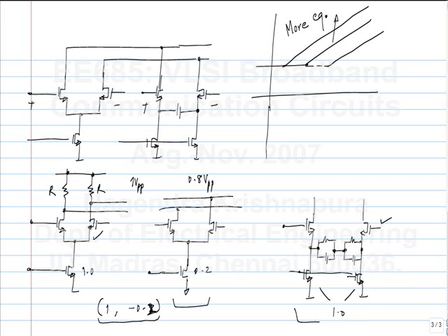Maybe this will consume lower power for a simple equalizer like this. But the advantage of the FIR equalizer is that you can make more complicated responses. So even if you get a lot of boost from this kind of circuit, you don't have control over the response. Meaning you will only get a response that is like this. You will not get a response that perhaps does this. Whereas with an FIR with sufficient number of taps, maybe you can get that. So for a simple equalizer, perhaps this would be preferred because you don't have to do anything, and perhaps it can also be realized with a little lower power. Okay. But if you want many taps of response, it's probably best to implement the digital equalization.